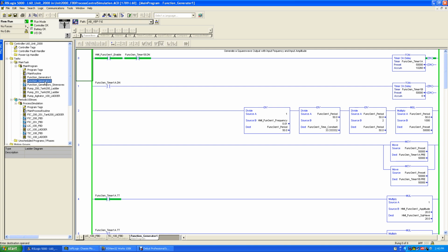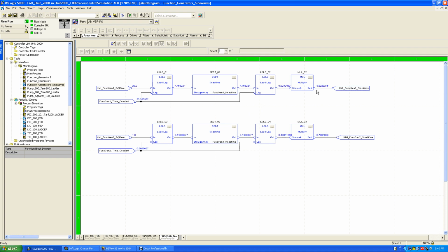So 2 function generators, and they're changing from plus minus 1, and these create disturbances, which I use in a different process. I'll show you later. So it goes positive 1, negative 1, and then here's the function generator, and you'll see what's coming out of the function generator. This is in the main program because it's not important how quickly it changes. Why I have a 100 millisecond periodic over here for all the analogs.